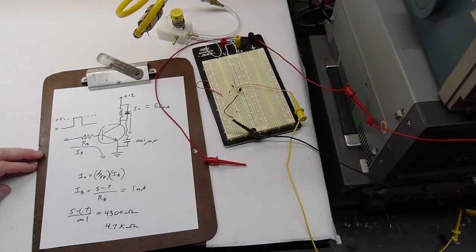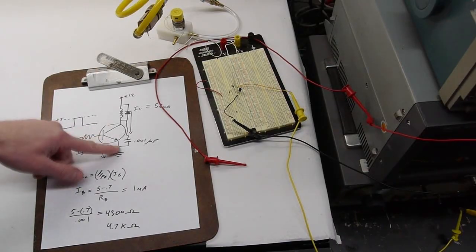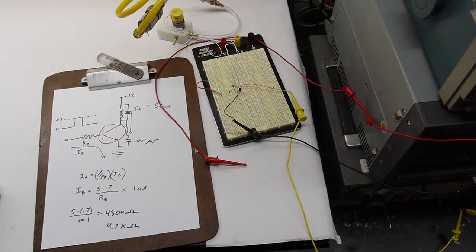In fact, when I was getting started in electronics, I thought a transistor was basically just a voltage controlled device. And so yeah, I put 5 volts on that base, and oddly enough, it didn't do anything. It didn't switch. It didn't allow current to flow. So I tried another one, same thing. And I thought, man, these transistors are just totally defective. But as it turns out, they were just being destroyed instantly. So you have to have a base resistor here.